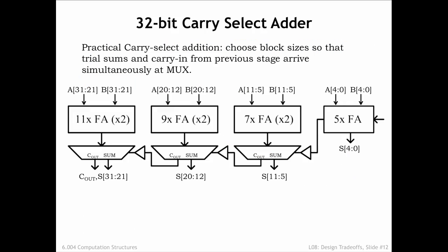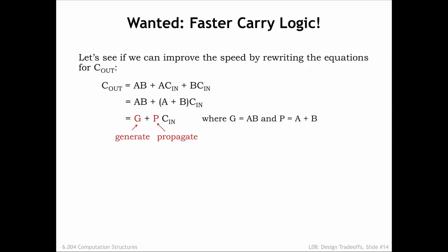Since adders play a big role in many digital systems, here's another approach to improving the latency of our adder, this time focusing just on the carry logic. Early on in the course, we learned that by going from a chain of logic gates to a tree of logic gates, we could go from a linear latency to a logarithmic latency. Let's try to do that here.